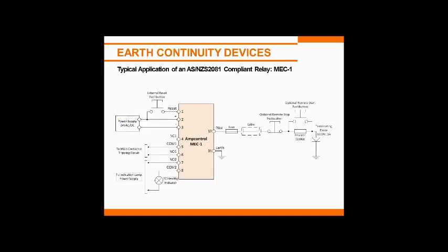Okay, so here's a typical setup of the circuit. A power supply, 24 volts AC or DC. Certainly the industry seems to be heading towards limited voltage for the control voltage, so a very safe voltage. 24 volts is something we're settling on, and most of the industry is now. A reset button, that's the external reset, is held there. The pilot lead and the earth lead are the basic interface to the outside world.